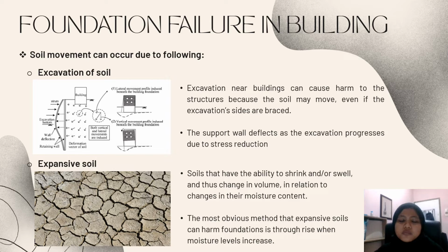After that is the expansive soil. Okay, so what is the expansive soil? Expansive soil is the soil that has the ability to shrink and swell, and thus change in volume in relation to change in the moisture content. The most obvious method that expansive soil can harm foundation is through the rise when moisture level increases. Swelling soils can raise and fracture slightly loaded, continuous strip footings, as well as produce distress in floor slab.